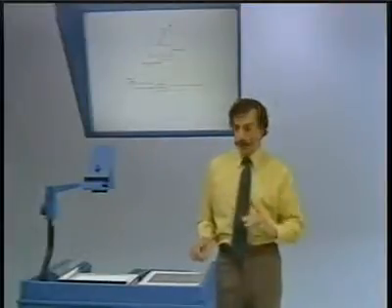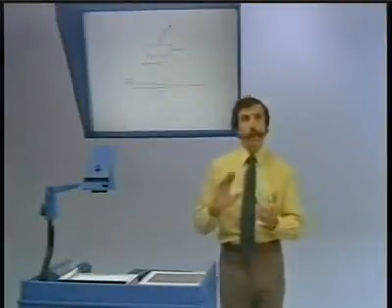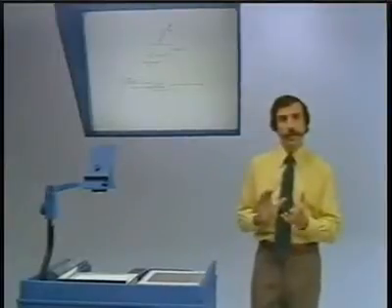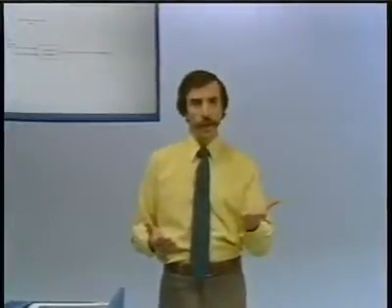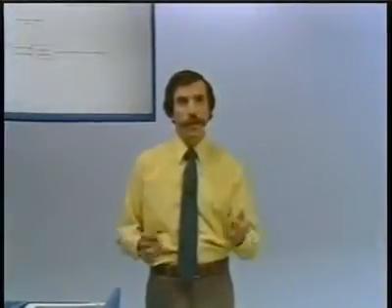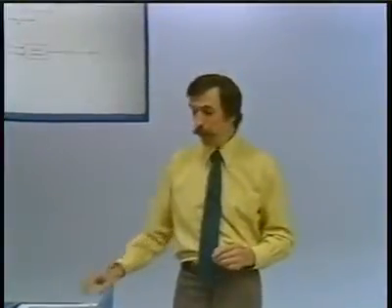Now, as I've mentioned several times previously, if we know exactly what the system dynamics are, and if we know exactly what the external disturbances are, then theoretically we can choose an acceleration for the cart which will exactly balance the system, or balance the rod. However, since the system is inherently unstable, any deviation from that model, in particular any unanticipated external disturbances, will excite the instability, and what that means is that the rod will fall.